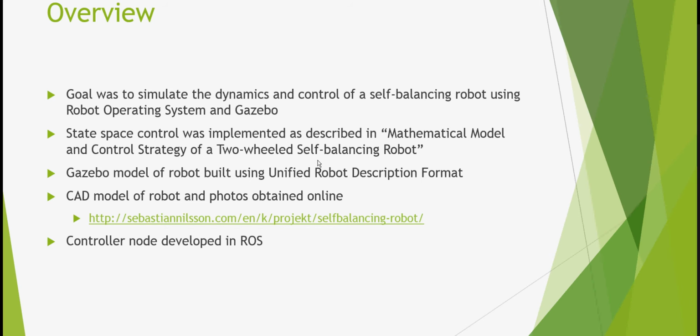The Gazebo model of the robot was built using Unified Robot Description Format, URDF. The CAD model of the robot and photos were obtained online through that website. They were imported into SolidWorks and converted to .stl mesh. The controller node was developed in ROS.